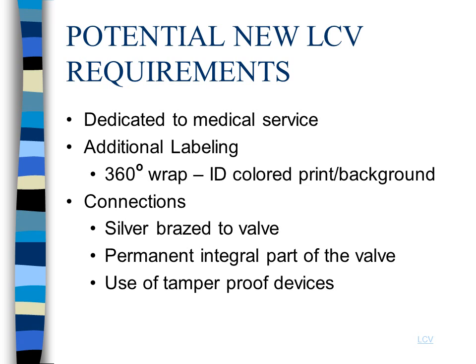When we look at the permanent integral part of the valve, what they're talking about is the outlet of that valve. Not too long ago, what the DOT and the FDA wanted was that outlet silver brazed to the valve.